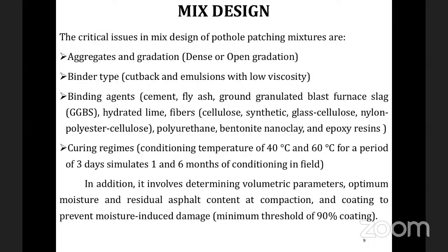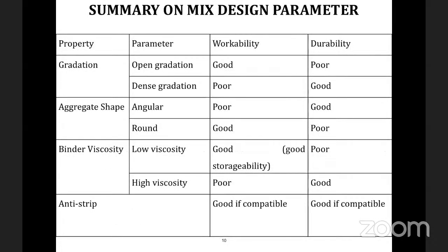This curing regime simulates 1 to 6 months of conditioning in the field. After the curing regime, it also involves evaluation of some volumetric properties: optimum moisture content, since it is a cold mix, and asphalt content and coating, that is moisture damage, which should have a minimum threshold of 90% coating. So this is the summary of the mix design parameters.